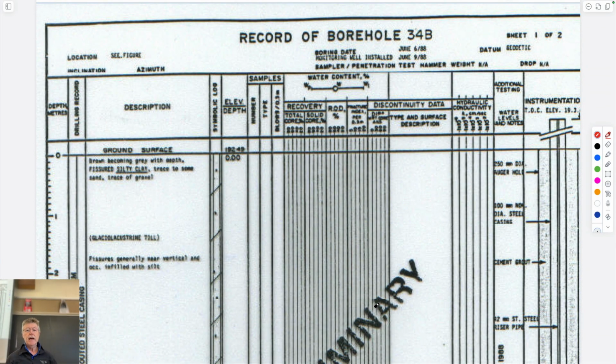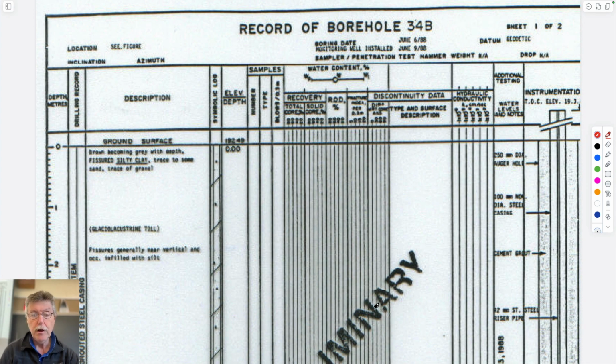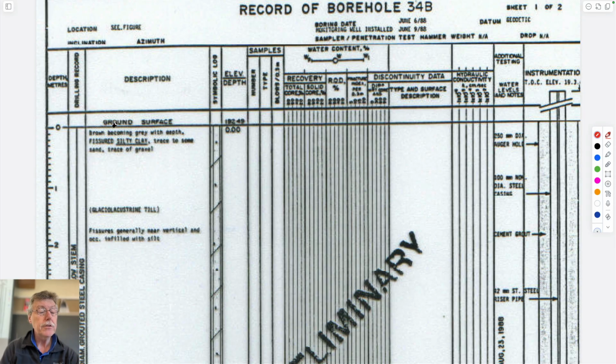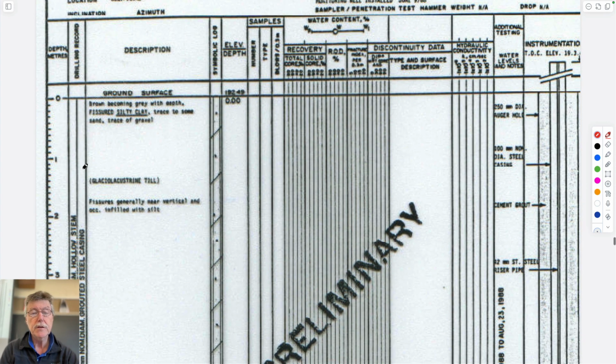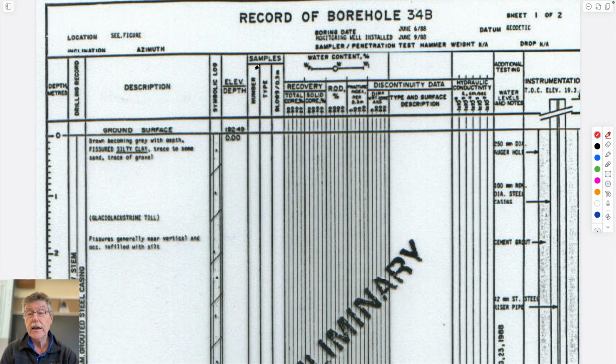So in line with getting advanced, with getting samples, I guess the other thing is that you'd like to get the most out of the hole as possible. So typically a borehole log would come along with that, and you, as an entry-level engineer or scientist, might be tasked with logging the things that come out of the hole. The driller just drills, and the driller helper just helps retrieve the material, but you're the person who decides what's going on. And so everything would typically go down in a log. This is a log, actually, I think, for Smithville.